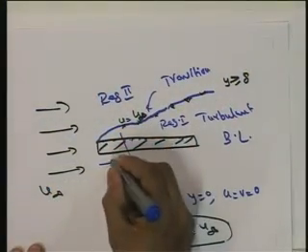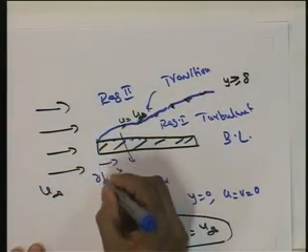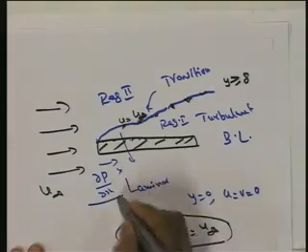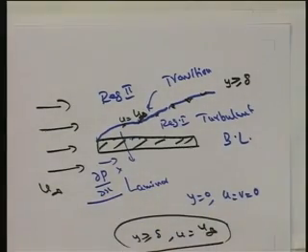According to Blasius, this pressure gradient del P by del x in the x direction, that means in this direction, the x direction is here, must vanish as far as flow over a flat plate is concerned. So, Blasius reformulated the Prandtl boundary layer equations, and for the boundary layer the equations were changed in this way.